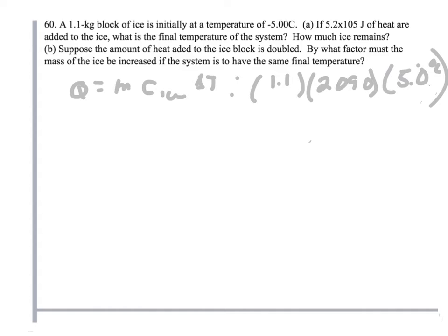And then that comes out to 1.15 times 10 to the 4, and that's in joules. That's how big Q1 is. So for our second amount, now we're changing. Now we're on that flat line where we're changing from ice to water. So we need the latent heat of fusion is what we want to calculate here.